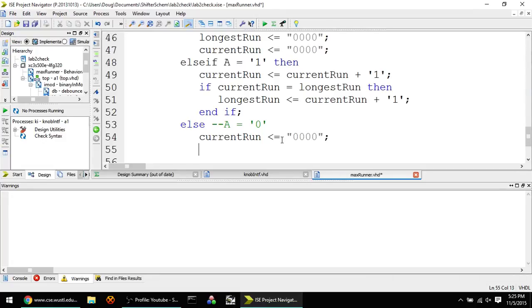And what is the name of the architecture? I don't even remember. Behavioral. Okay. Oh, it's already there. Okay, cool. Don't need it. You'll get one syntax error because the HDL doesn't understand what else if is. It's ELSIF. Oh, thank you, which is so confusing. Why that was ever the decision. Yep. Okay. You should write them a strongly worded letter.